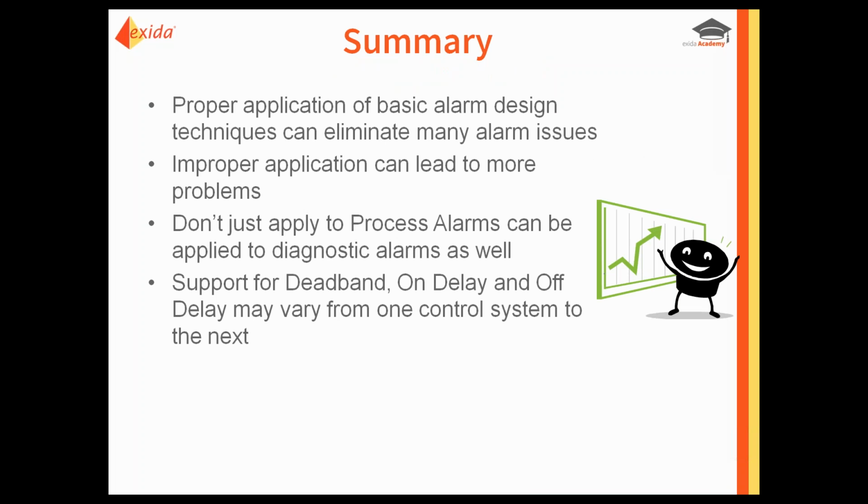So now, reaching the end of our discussion here and looking at some of the key takeaways. Hopefully you've seen that the proper application of basic alarm design techniques, particularly deadband and on delay and off delay, can eliminate some of the most vexing alarm management issues like nuisance alarms. We can eliminate stale alarms. We can eliminate chattering alarms through that, thus making the alarm system a more viable tool for the operator to use.